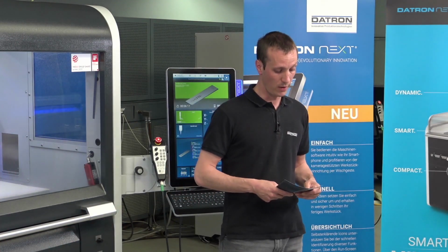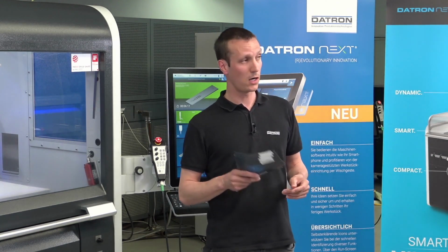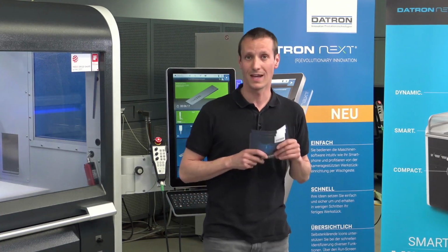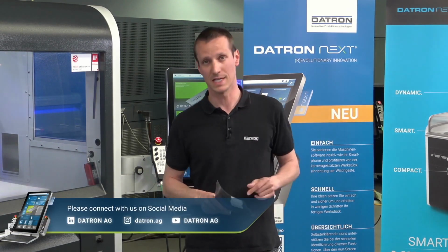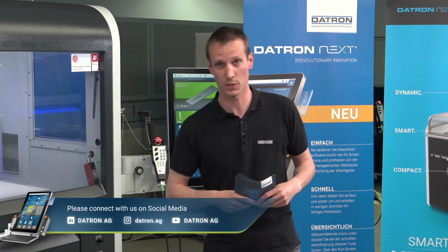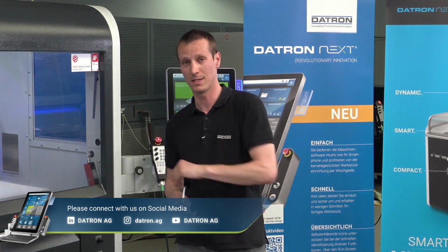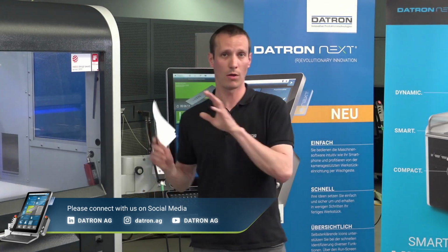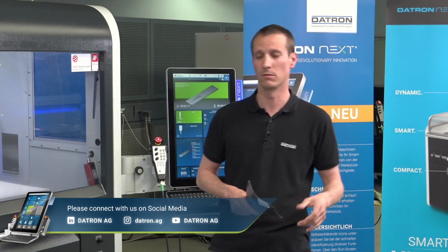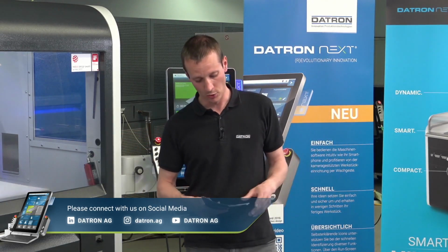That's just important to know. Does the software save the rotation angle in its entire origin and its workpiece offset? Yes, it does. I think this question comes from someone who used to work on the older machines where we just have the X, Y, and Z value. On the next controls, we also save rotations, scaling, all the kinds of information that you have. Super handy. So if you have a special fixture at a certain angle, it will always be loaded again.